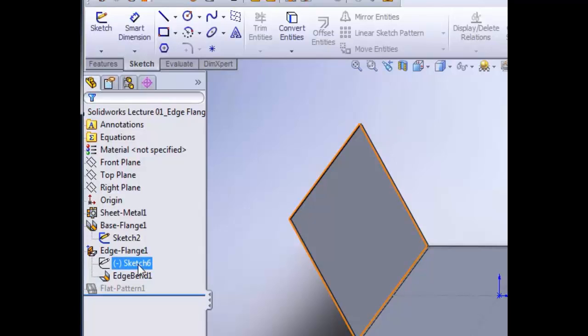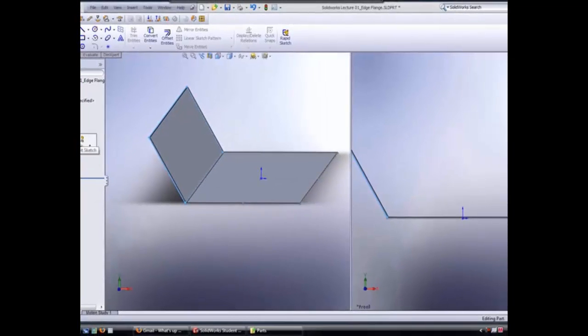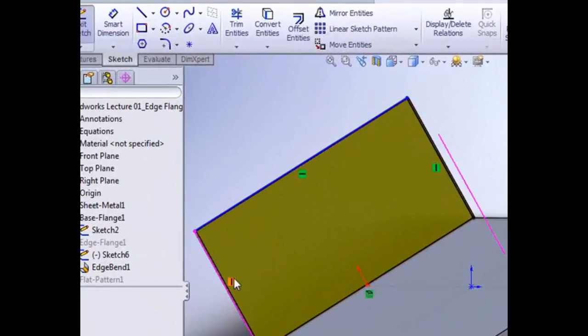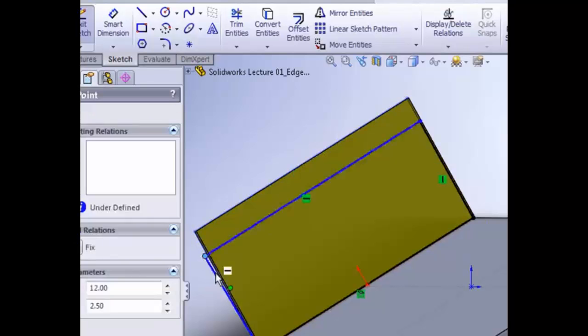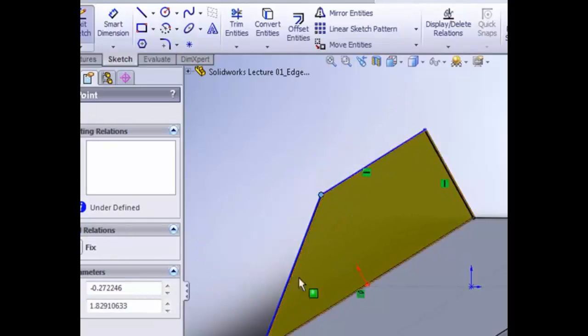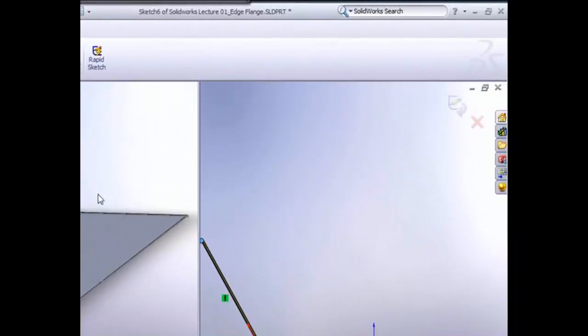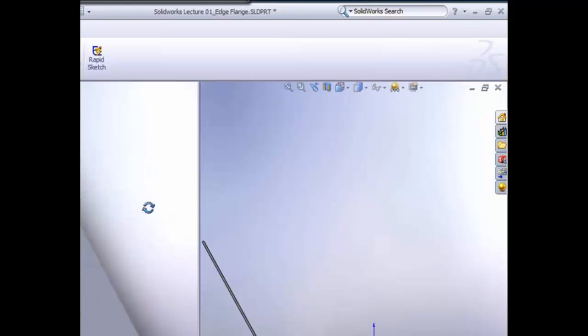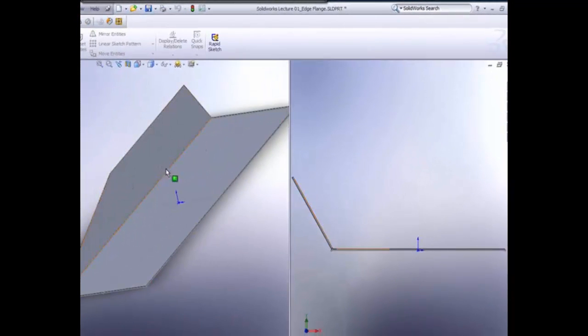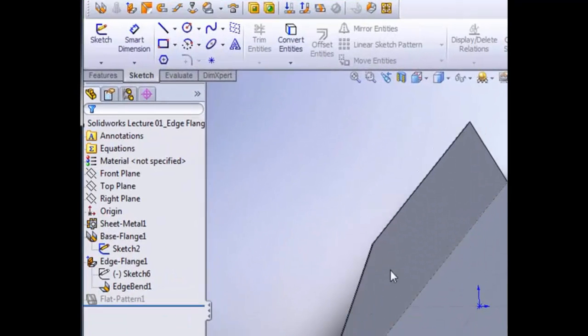One other thing about the sketch, we're not going to go into this so much, but if you open up this sketch relationship, edit sketch, just like we had done before, you can delete some of these geometric relationships and actually begin to change the shape of this flange. All right, so you can have a high level of editorial capabilities with this flange. Now all of a sudden we've created a notch there, and there are ways to be much more didactic about how you create something like that. But we are not actually going to be editing flanges at the sketch level.